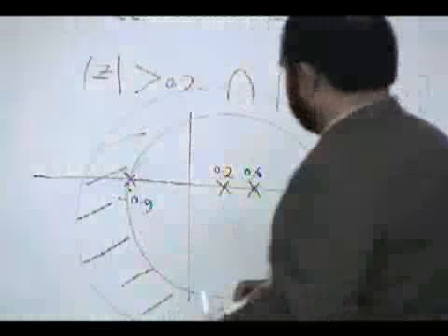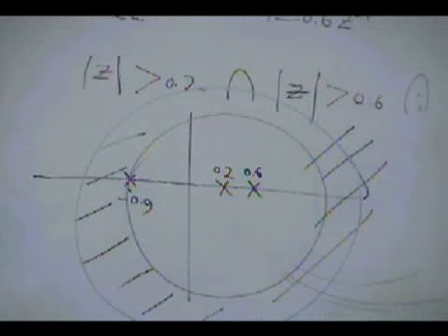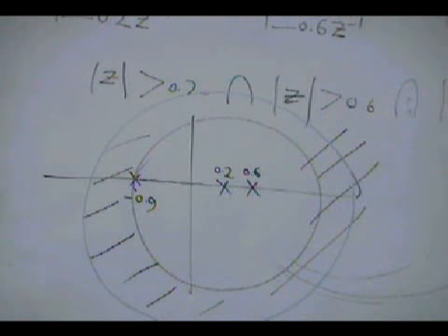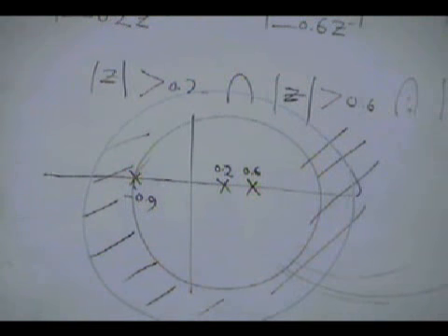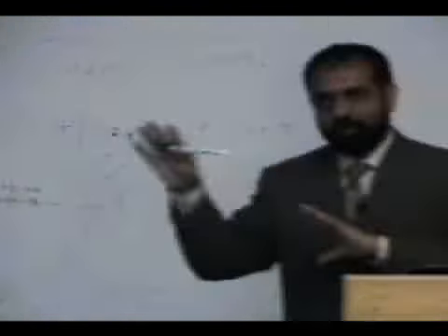Is it inside the region of convergence? Answer is yes. Very easy check for stability. Usually we will have right hand side sequences, because a left hand side sequence is not causal. It requires future samples. So we know that h of n in the negative direction means non-causal, requires future samples.